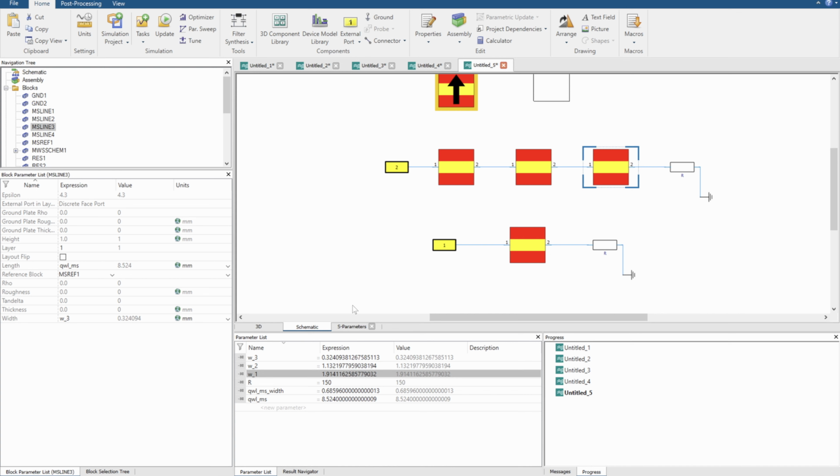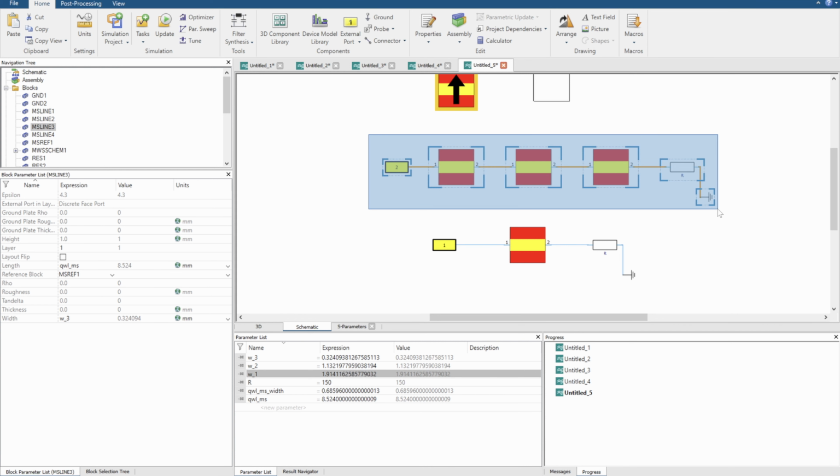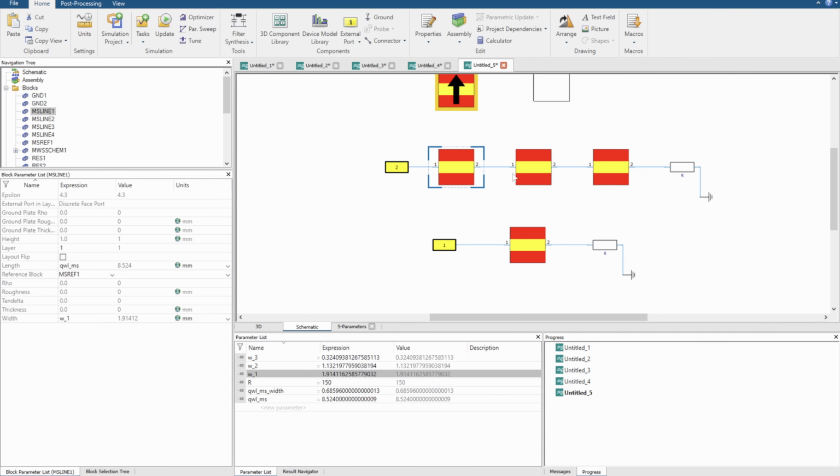I've previously done a 12th order through optimization and was able to achieve a good result. So it is possible. However, learning this from the textbook and implementing the textbook's impedances will definitely achieve a cleaner solution. However, this is a very quick and easy way to do wideband impedance matching networks.